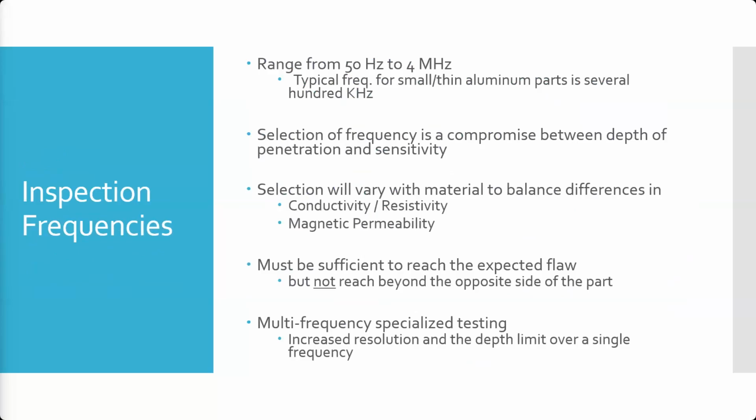We're going to be looking at working in the kilohertz or megahertz range. You can see we do have some probes that go down into the hertz range, right? Like that big coil probe there. But because we're using this primarily on aluminum parts, titanium parts, magnesium parts in aviation, we're going to be working with those higher frequencies.